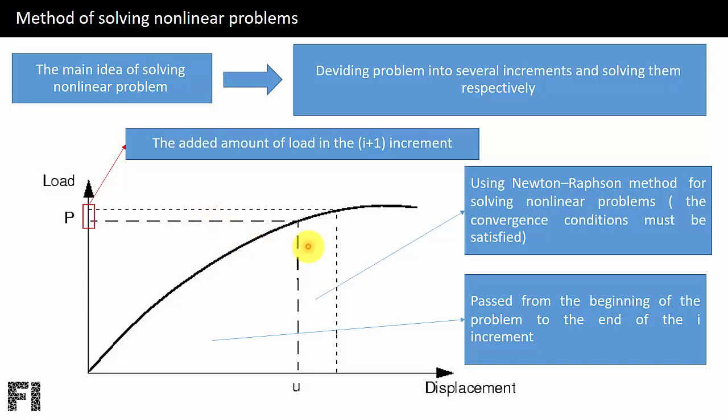For solving nonlinear problems, Abaqus standard uses Newton-Raphson method. This method is so famous, and in the courses for numerical calculations, this method will be taught. This part is passed from the beginning of the problem to the end of the I increment.